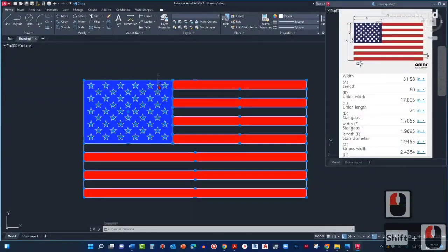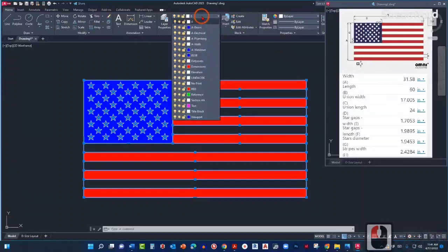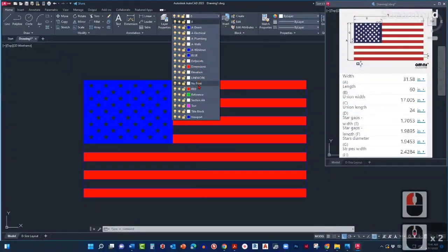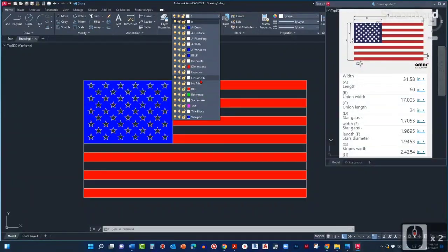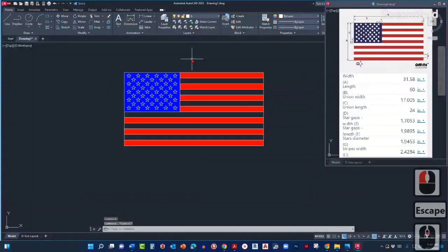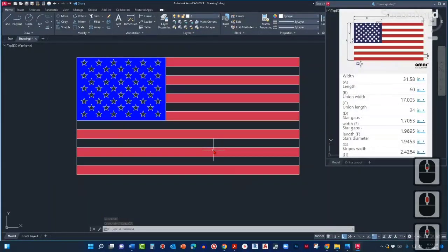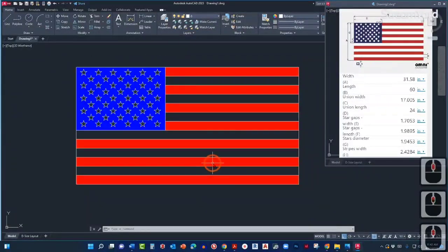Let's select this other blue hatch, and deselect it. Again, we are ready to place them on the correct layer, in this case, line work. Where is line work? It's right here. All right, everything is now ready to show you how to export your drawing as a PDF.